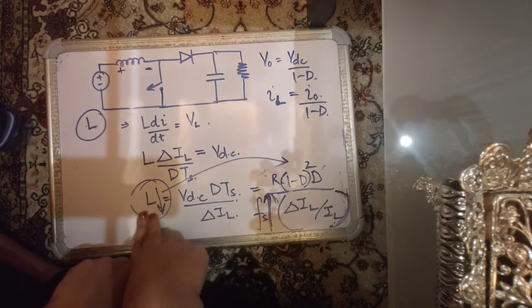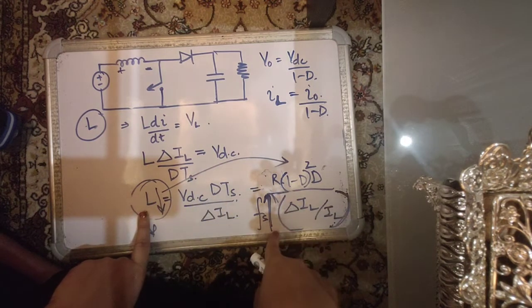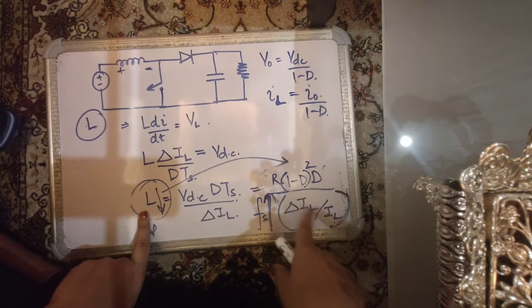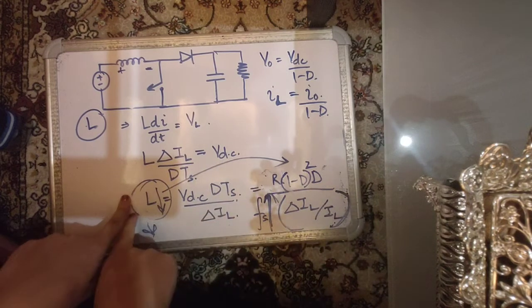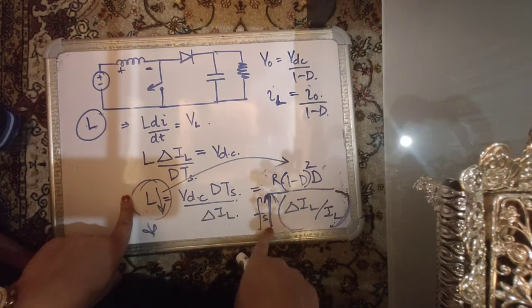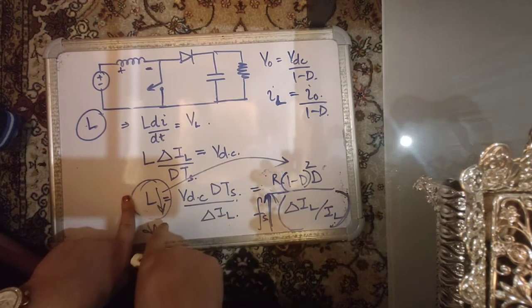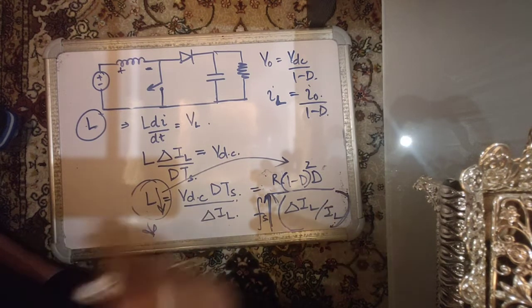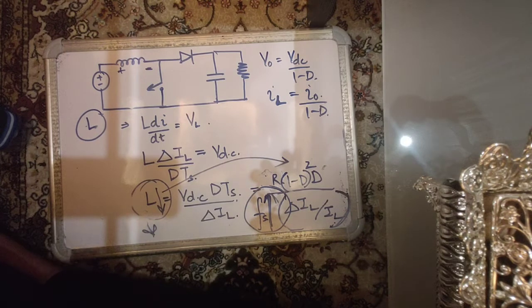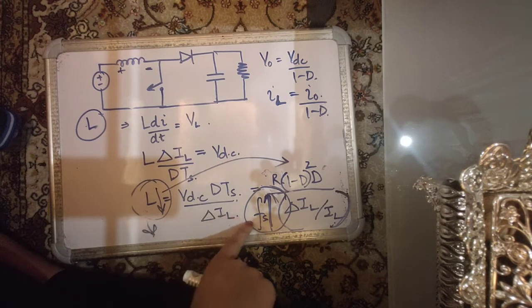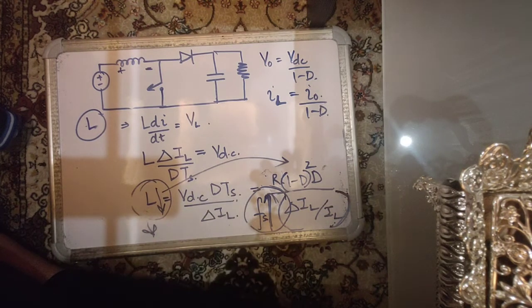But if with the same 1 millihenry you go to 20 kilohertz, your ripple will fall. Because, you see, these are all interconnected. If you write this equation in terms of ripple, it will have an inverse relationship with frequency or with inductor. So generally it is always desired that you go to a high switching frequency, but not create so many losses that you burn out your device. So high switching frequency is again desirable in a boost converter, right?